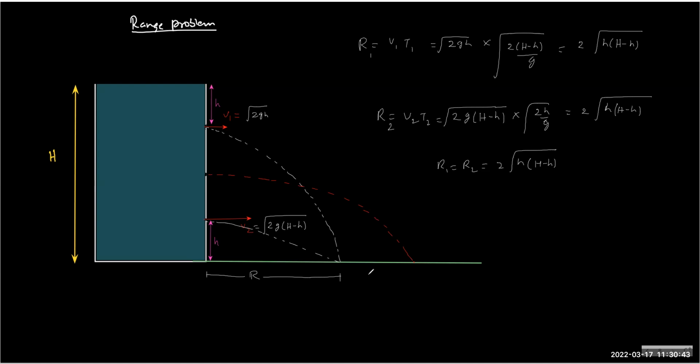Okay, understood? And the maximum range is how much? This will be 2h. No, sorry, H. Because it is H by 2, H by 2, H by 4, yeah, H. So if I maintain the liquid level always at H by attaching a tap here, this tap will always keep this vessel filled, and the maximum range cannot exceed the height.